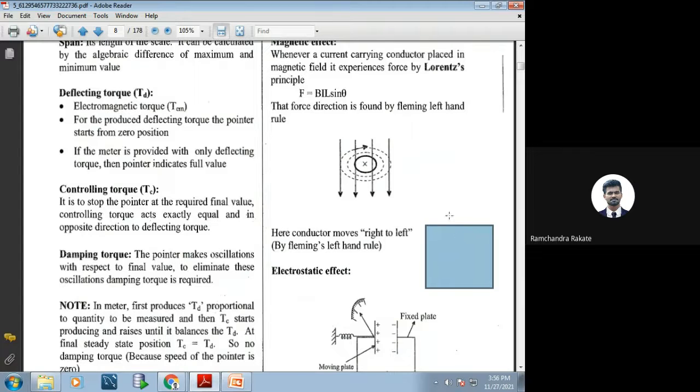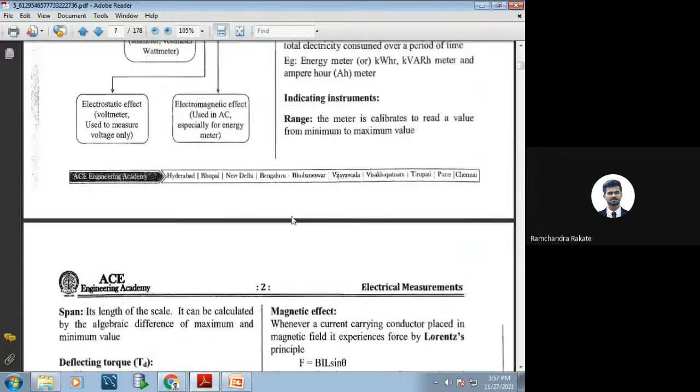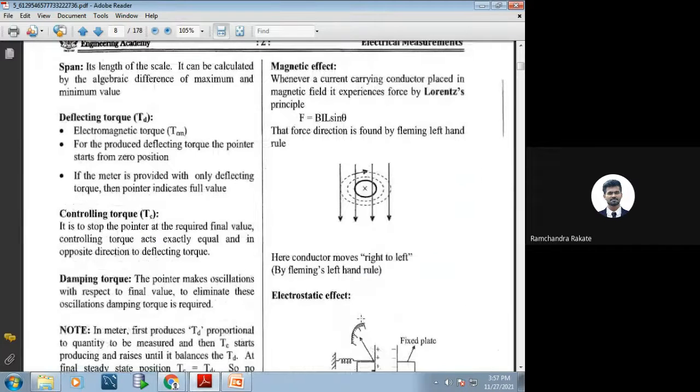It has a capacity of 100 kg, and a person who is standing over there has a weight of 107 kg. So the weighing machine will show full scale deflection. It means that whatever load we applied on that instrument is out of range. That's why it is showing full scale, because after this full scale we cannot proceed further.